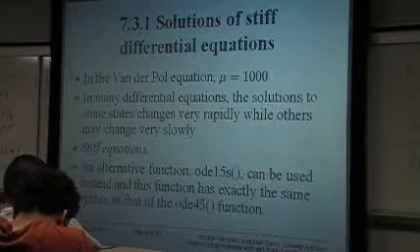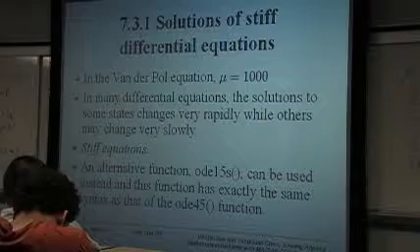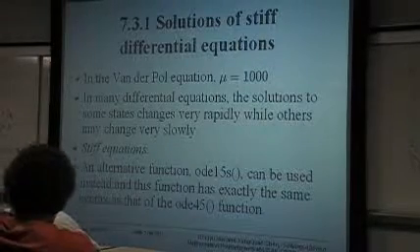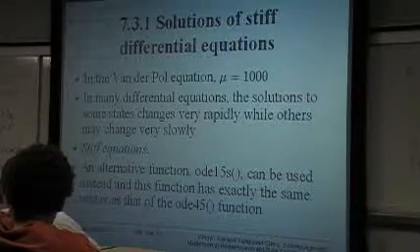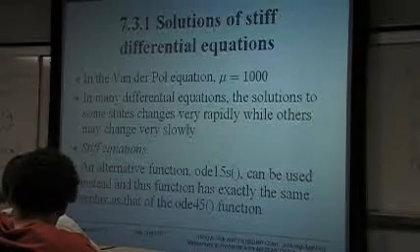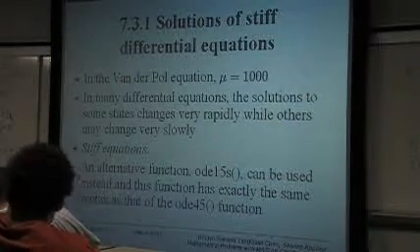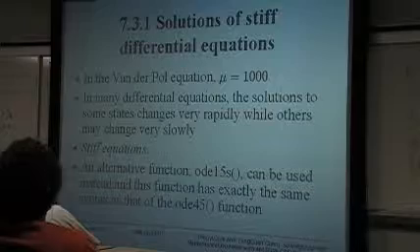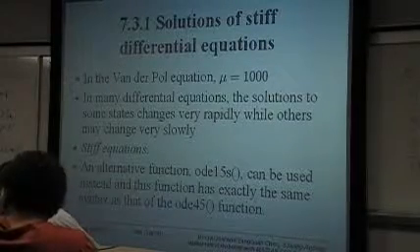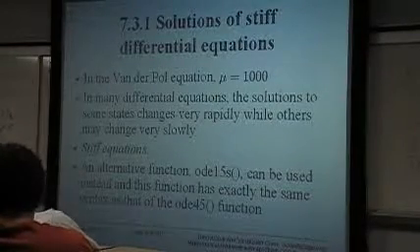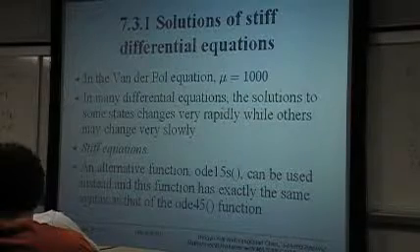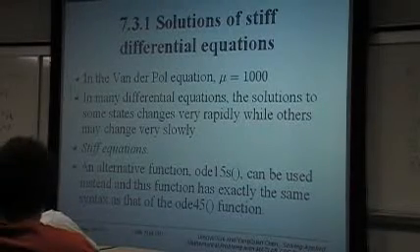So for this kind of problem, we cannot use ODE45. We have to use specialized functions for stiff equations. For instance, there is a solver called ODE15S, where S stands for stiff.